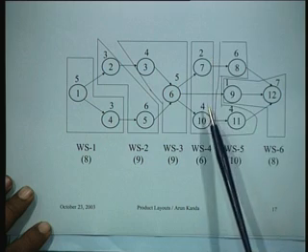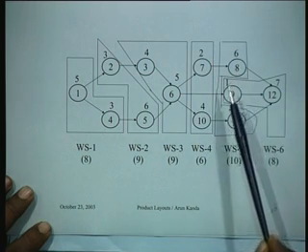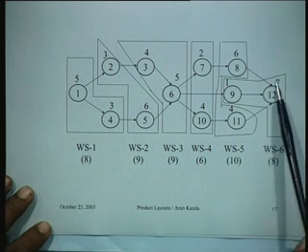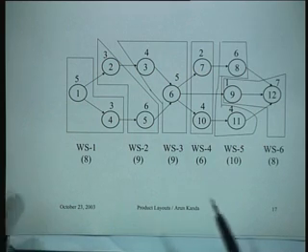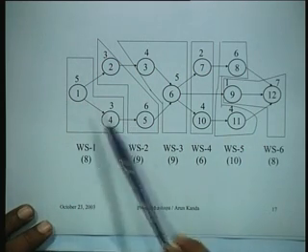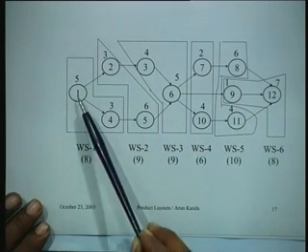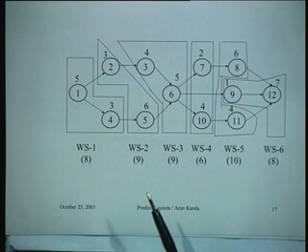This takes 2 plus 4, which is 6. This takes 6 plus 4, which is 10. And this takes 7 plus 1, which is 8. So by simply grouping parts, the objective is that the sum of the times in each group must not exceed 10.